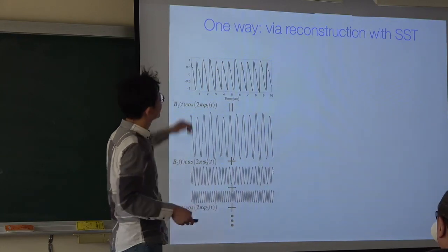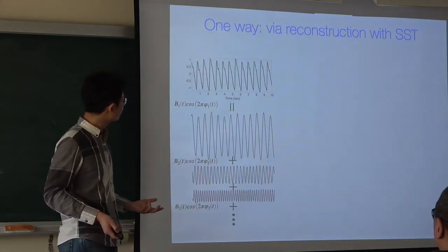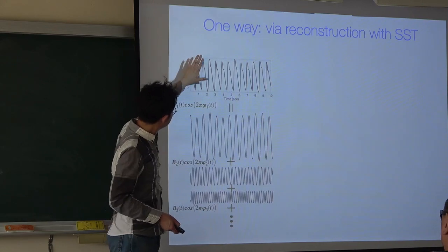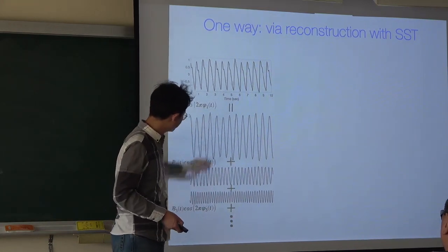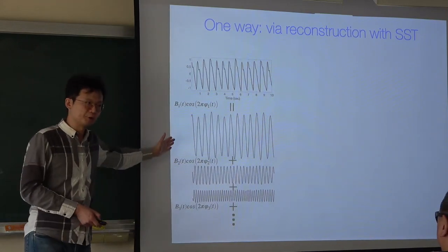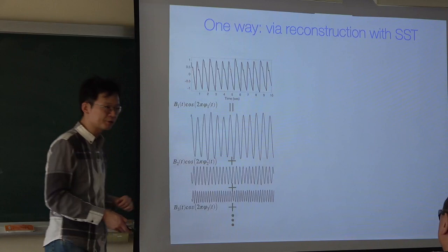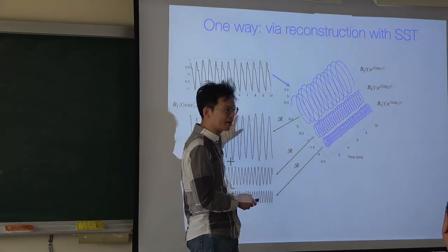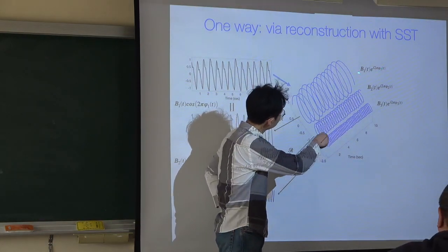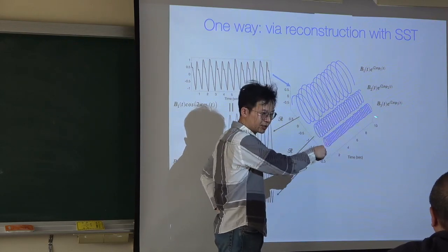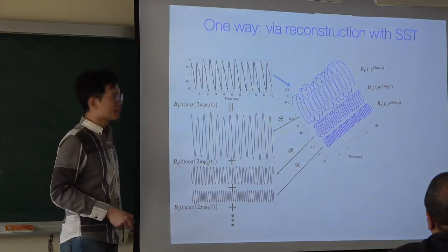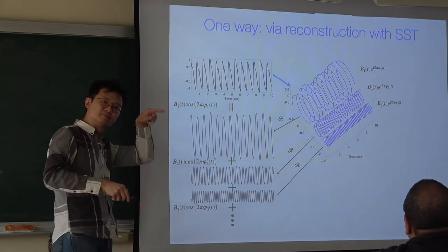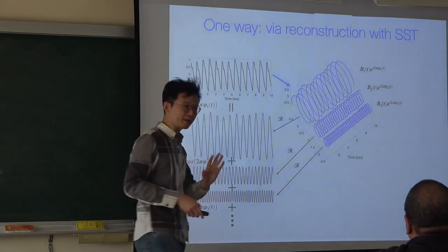So if we use the generalized adaptive non-harmonic model I showed you and do this decomposition, this is the PPG signal, and you decompose it into the first fundamental component, second harmonic, third harmonic. Very good, right? Just like cosine with some amplitude modulation. Now, we know that all these components come from the reconstructed one, and the reconstructed one is in a complex form, as we discussed before in synchrosqueezing. So you can see that in the complex domain they have a nice circle. So far so good.